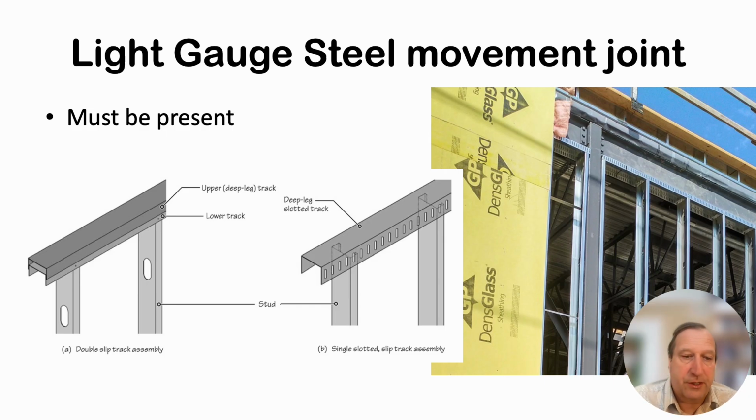So the steel stud systems often use slotted holes, as you can see in the photograph, or you can use two nested C's, one on top of the other, that allows movement. And the primary responsibility for identifying how big that gap should be is the engineer of record for the structure, who says expect 19 millimeters or 3/4 inches of deflection. Okay, the person who designs the steel stud and installs it then has to accommodate that 19 millimeters of movement. So there's a bit of coordination that has to happen there.